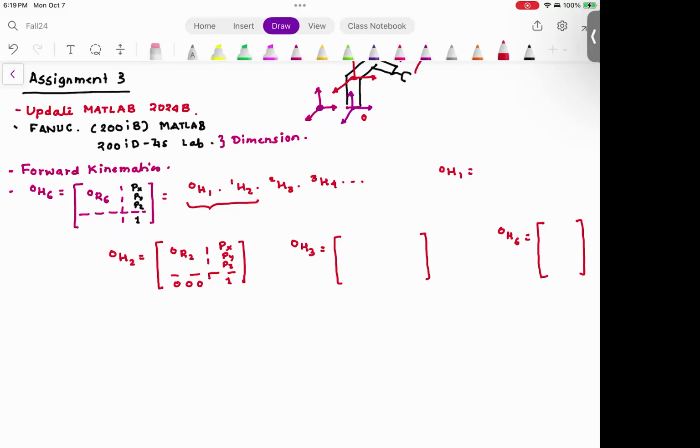You can also go from the end effector all the way to the coordinate frame. That's also fine, but then you don't know if your intermediate poses are correct or not. So finally, your end effector will be at the same location, but your intermediate joints would be at different locations. I'll let you figure out what happens. There is something else that would happen.